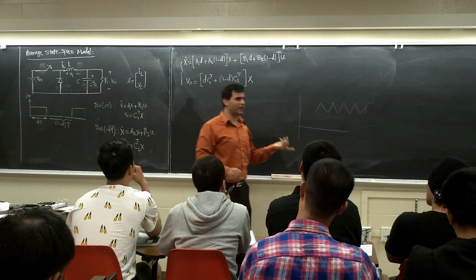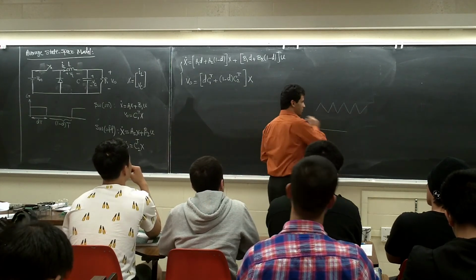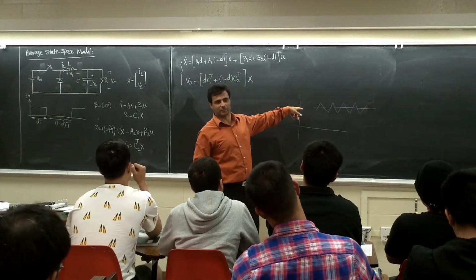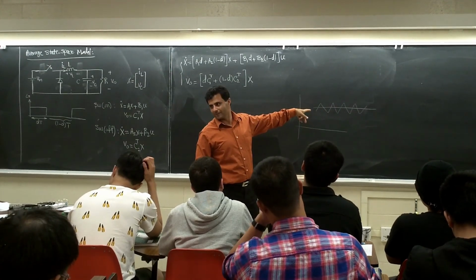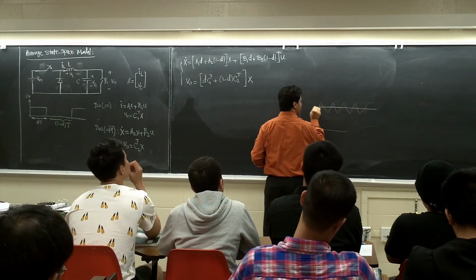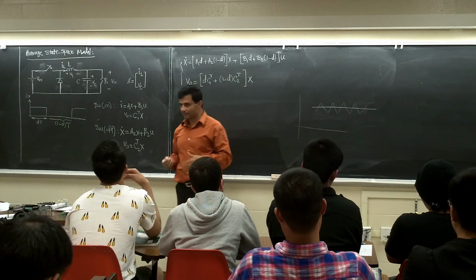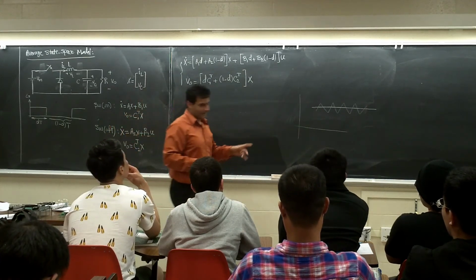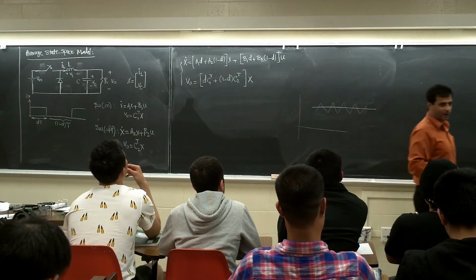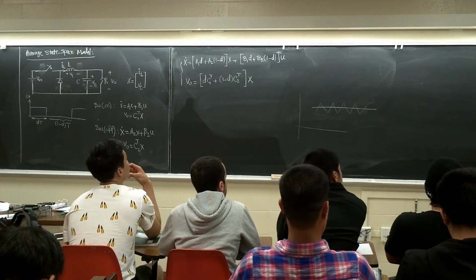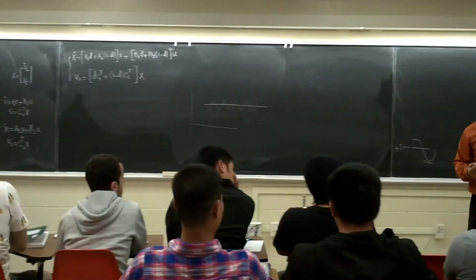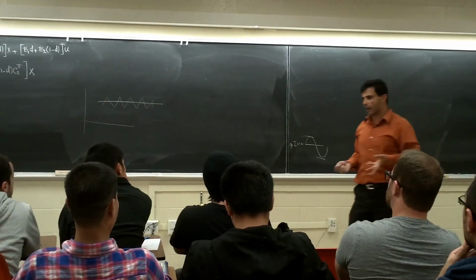I'm telling you, I cannot tell you exactly how much it is, but by this equation I give you the average of this value, right? This method is going to give me this one because I averaged it out. But this is the real current. It's not going to give me the real current. They call it the average method. It's not going to go to the detail of switching, but for control purposes, it's okay.